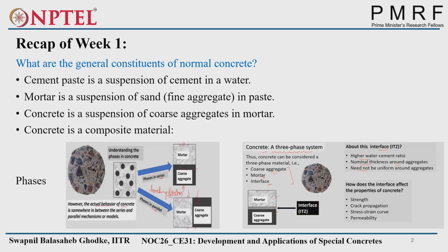Yeah, it's sufficient, no doubt, because it's giving high strength, as we see in high strength concrete, because of the lower water cement ratio. But whatever extra cement is available apart from the hydrated cement, that cement will act as a filler. And because of the filler, whatever pores are there will get filled. And because of that, what is the strength dependent on? A large amount of pores means strength will be reduced. A smaller amount of pores, strength will be high. So that will act as a filler.